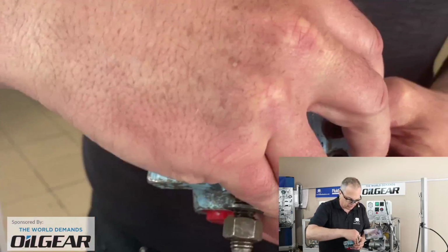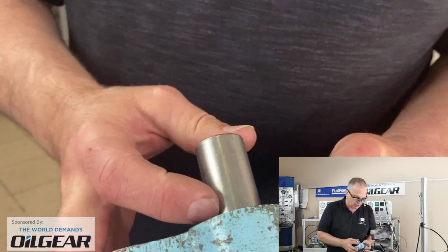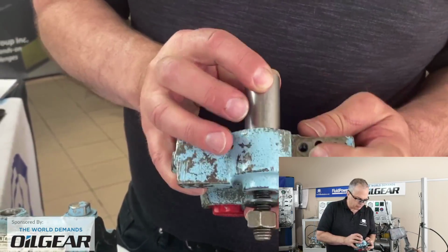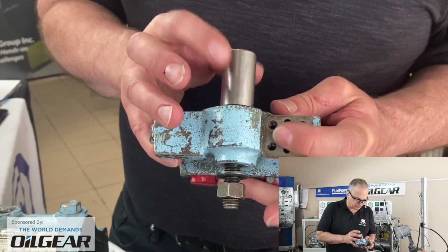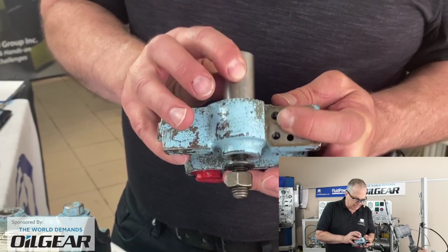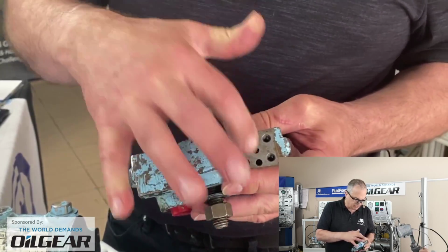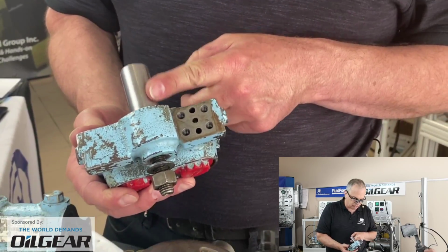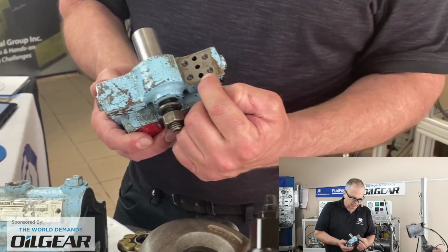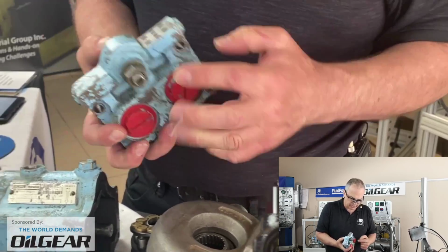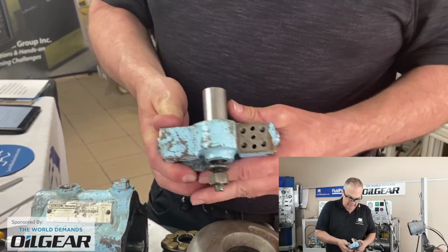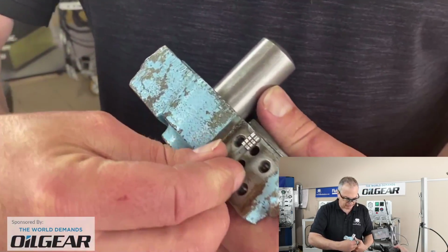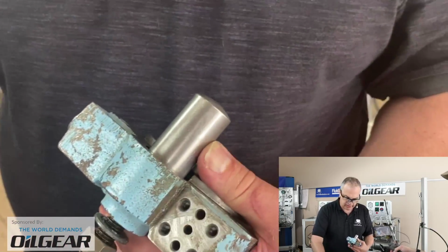By the way, it's easy to figure out from these three. Here's where the pressure compensator was sitting a few moments ago before I took it off. If you cover that one with your finger, no, it's this one in the middle here, you can see that that's clearly the one. I'm pumping a little air against my finger there. So that's the passage that directs fluid into the control piston to de-stroke the pump. And where does it come from? This passage back here, which is monitoring the pump's outlet port, through a little pressure compensator spool that sits inside the compensator.